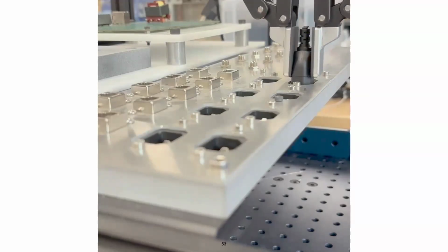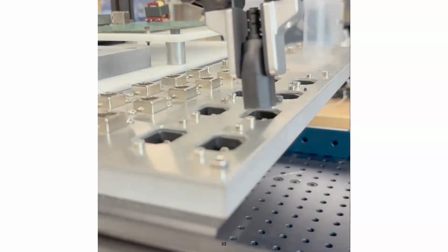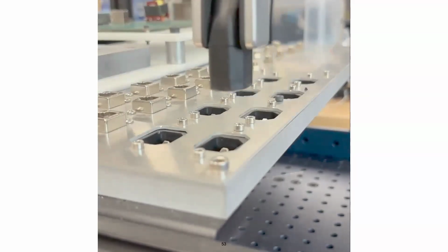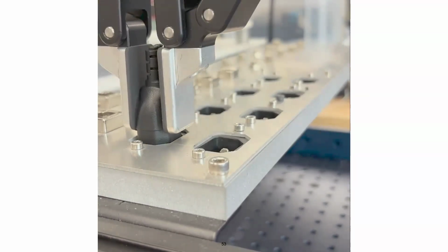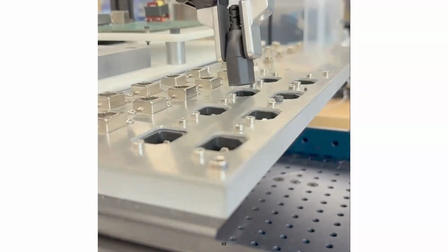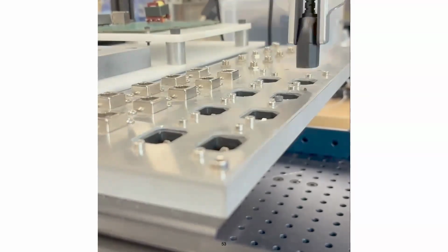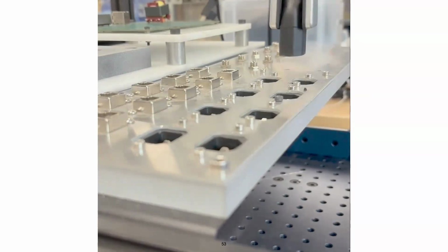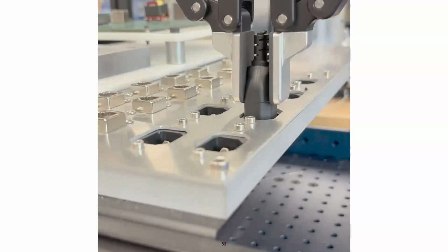And this works both in sim and on hardware. It actually worked on hardware first, which is extremely unlikely, but is true. So here we have an example where we're doing a bunch of plugs, and each one feels very different to a human. If I go plug things in, some are very stiff, some go a little bit deeper than others. So what we do is we go around and wiggle on each plug, and we learn this force torque mapping for each one. And then we can just guide these perfect insertions for each of them.